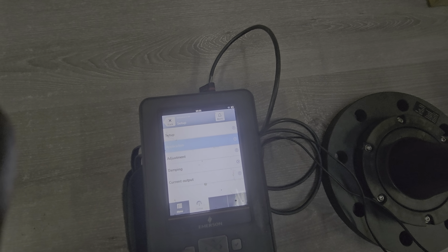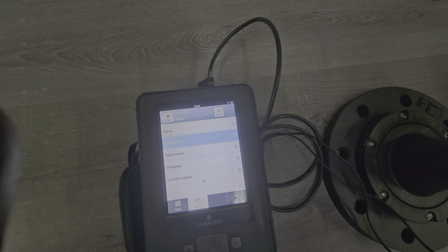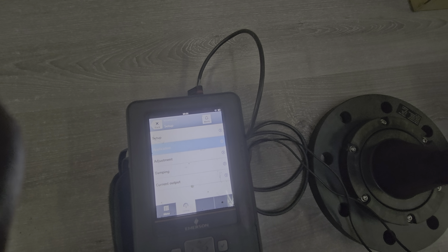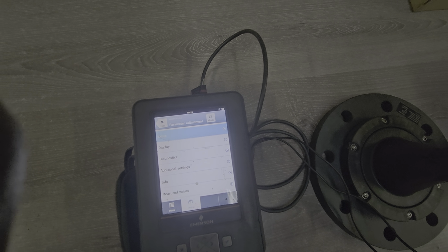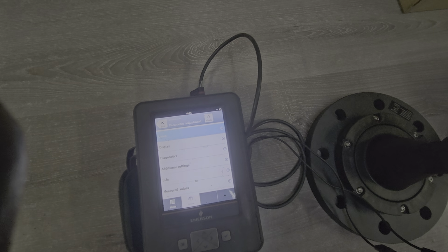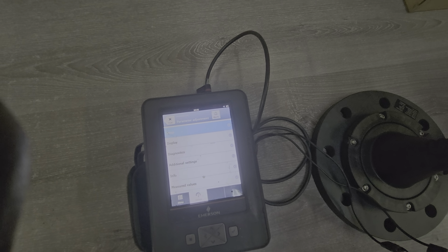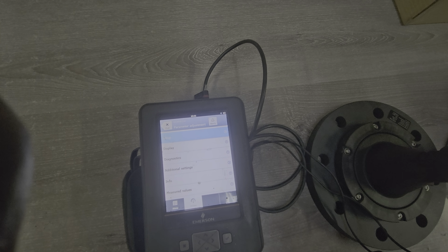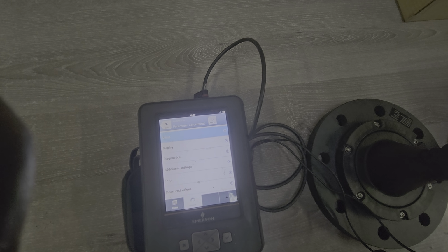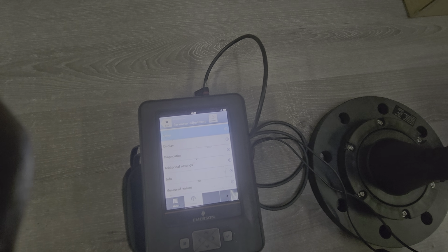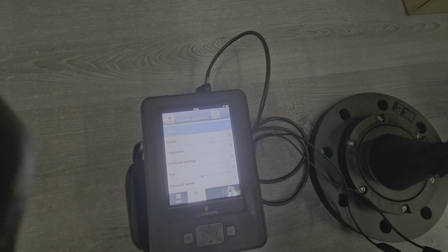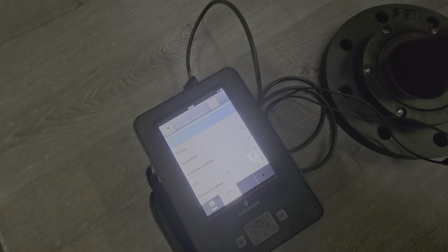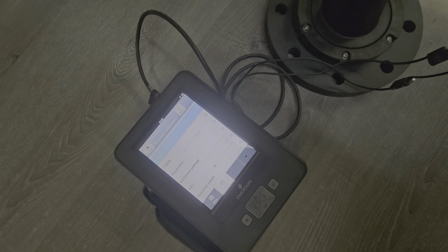Okay, there's a lot of settings, like I talked about damping, we talked about current. The current output, you can reverse it from 4 to 20 milliamps, or else you can do 20 to 4 milliamps. And then you can also set the fail state. If this instrument fails, do you want it to fail to a 0, which is less than 4 milliamps, or to a maximum, which is greater than 20 milliamps, or do you want it to restore the last value? So if the instrument was at 30 when it failed, it's going to fail and display that last value.